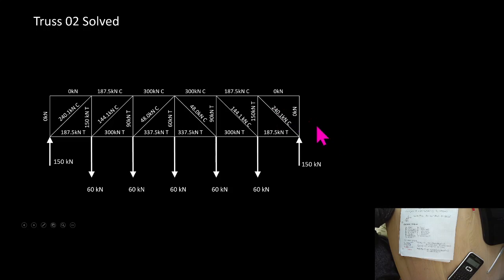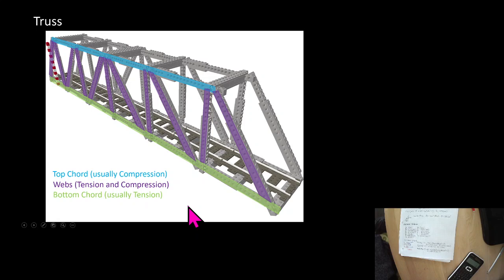If we made those go away, does this start to look like a familiar truss? We've got a truss shaped like this with the load coming in on the bottom chord. Remember, if this was a building, normally we'd be loading up the top. But this has load coming in on the bottom chord with 0 force in those corner members.